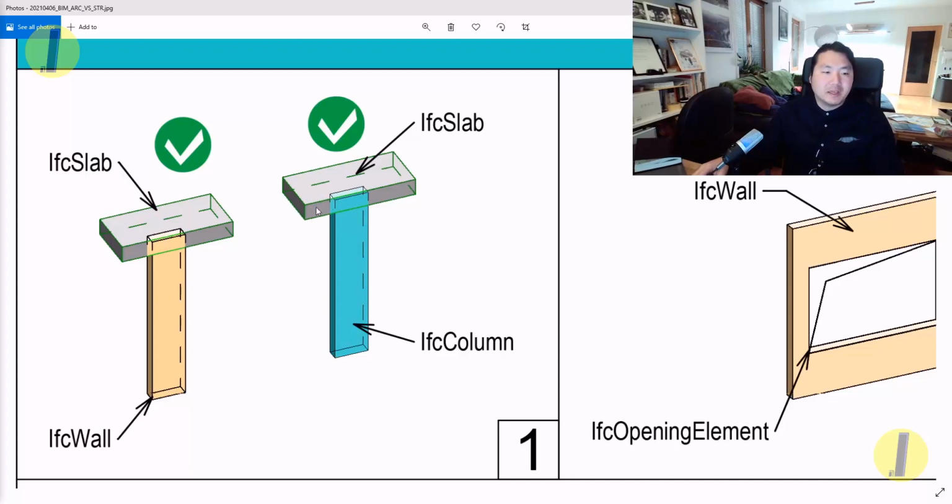But in most cases, structural engineers for this sort of case use a column for the structural analytical model, but at some point it is also used as a wall. So again, it's the formula of length divided by thickness, and that result depends on your national code. Maybe the architect models it as a wall or column, or the other way around by the structural engineer.